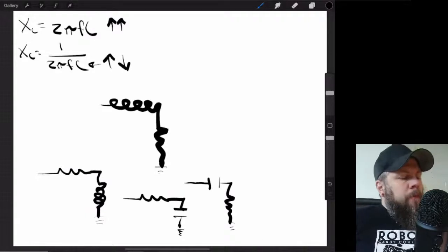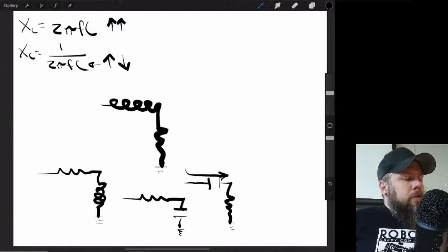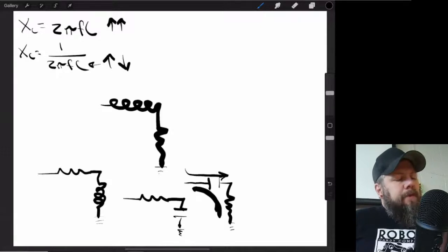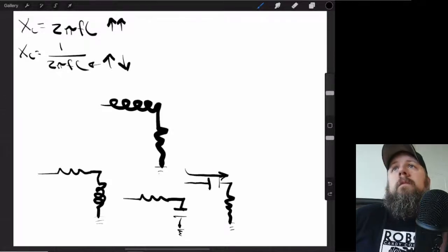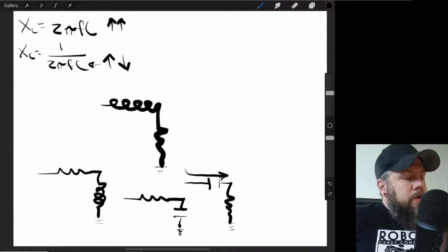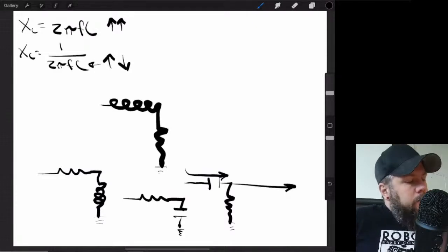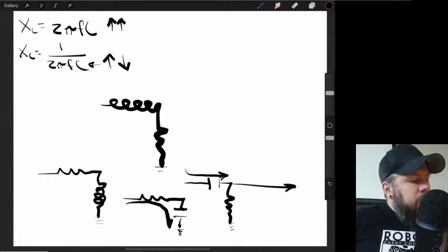Now, what do capacitors let through? They let through high frequencies a lot easier, correct? Okay, so this little network right here is providing a voltage divider, okay? And that voltage divider changes based off of the frequency that you put in it, all right? So what do you think is going to come out this side? More high frequencies than low frequencies, right? Okay, now look at this. I've got a voltage divider that changes.